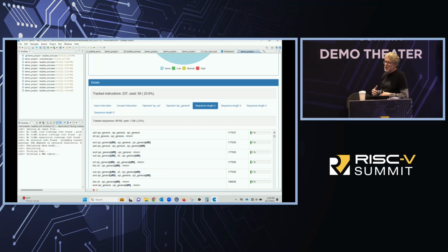Since I know this core, this particular instruction, I have the hardware resources to collapse these two instructions into one. Now, if you look at the first instruction, it's a subtraction. I have 0 minus another register, so I'm really taking the negative of a value. And we see the DF0, that means it's the same register number. So I'm taking the negative of a register, storing it in the same register.